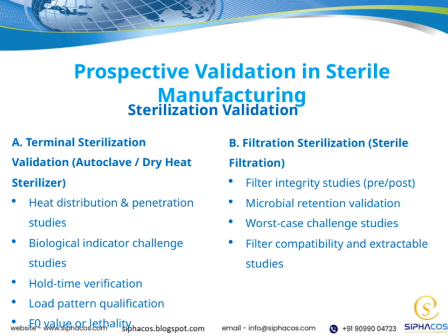Hold time verification ensures the product is maintained at the sterilization temperature for the appropriate duration. Load pattern qualification confirms that the way items are arranged allows for effective sterilization. Lastly, F0 value or lethality determination quantifies the sterilization process's effectiveness, providing a measurable parameter to ensure consistent sterilization. All of these steps are part of prospective validation in sterile manufacturing, which is crucial for maintaining high-quality standards and ensuring patient safety throughout the production process.